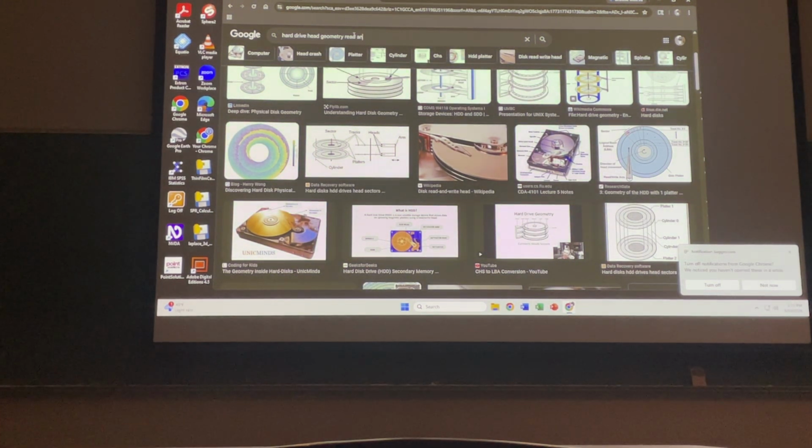Because remember, you have a laser in there. It has a focusing ability. It can go around and it takes in data and goes to a reading unit. So normally it's either a 1 or 0, but it's a very slight level. But what you do is you make it so that particular laser, which is 473 or something like that nanometers, or 455, it's very strong, can go and do fluorescence imaging on this platter.